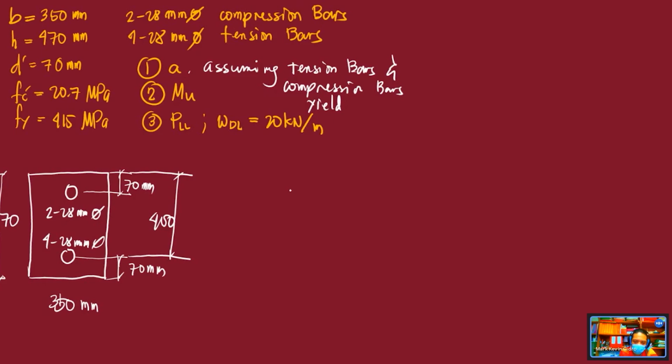The approach is in NSCP 2015. Of course, we can solve immediately for the value of a, as the step number 1 of our solution. But take note, we do not yet know if the beam is doubly or singly reinforced. So the first step is really to determine the value of a.